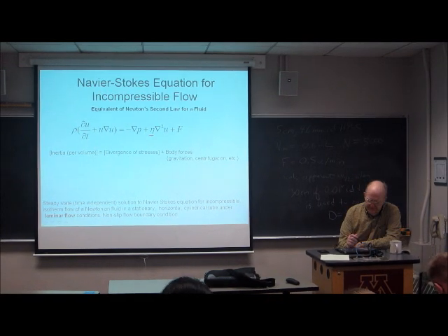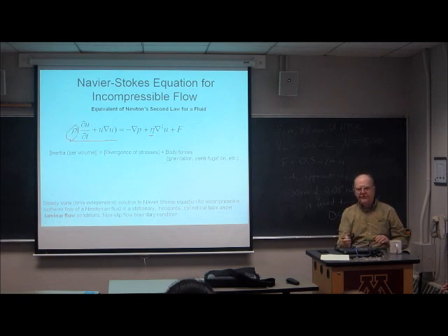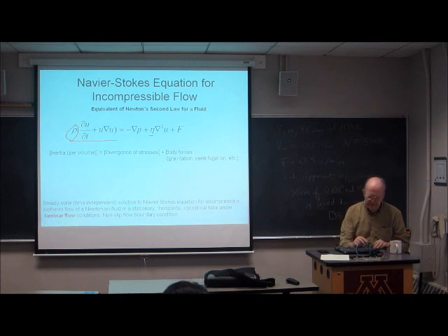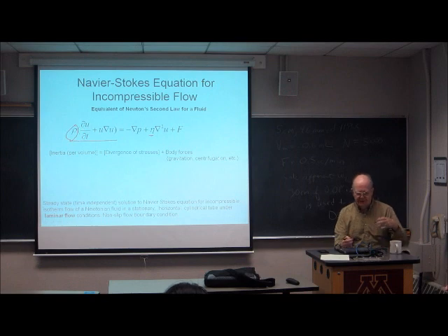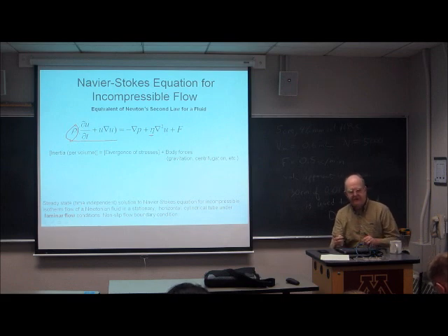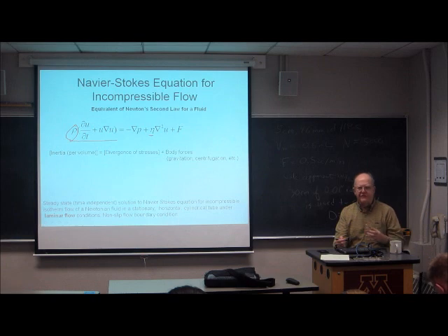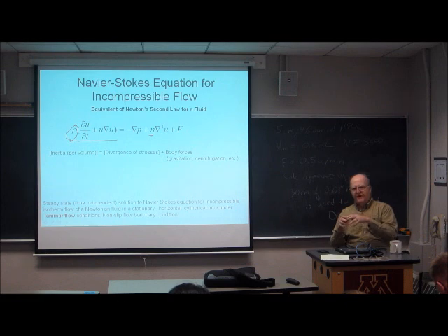This is the viscosity coefficient of whatever fluid we're talking about. In terms of the fundamental physics here, the left-hand side, this is the density of the fluid, which is equivalent to the M term, the mass term in the equation. So this side represents all of the inertial forces per unit volume in the fluid. The right-hand side are the driving forces and the dissipation forces that take place in the fluid.